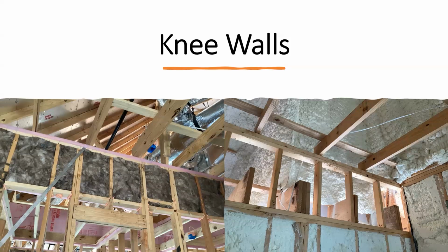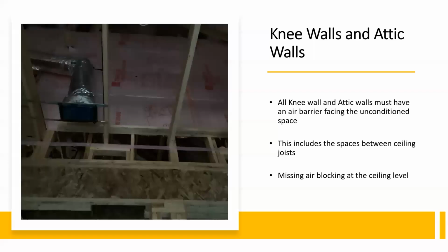This looks correct to most people doing the framing and doing the insulation. It looks correct, but if I went over that knee wall and jumped to the other side, that's either a garage or the outside, and that is not correct. It needs to be a complete alignment of the air barrier and the insulation for the thermal boundary. In my opinion, this is a misalignment. We'll see what that looks like later and why it's a misalignment.